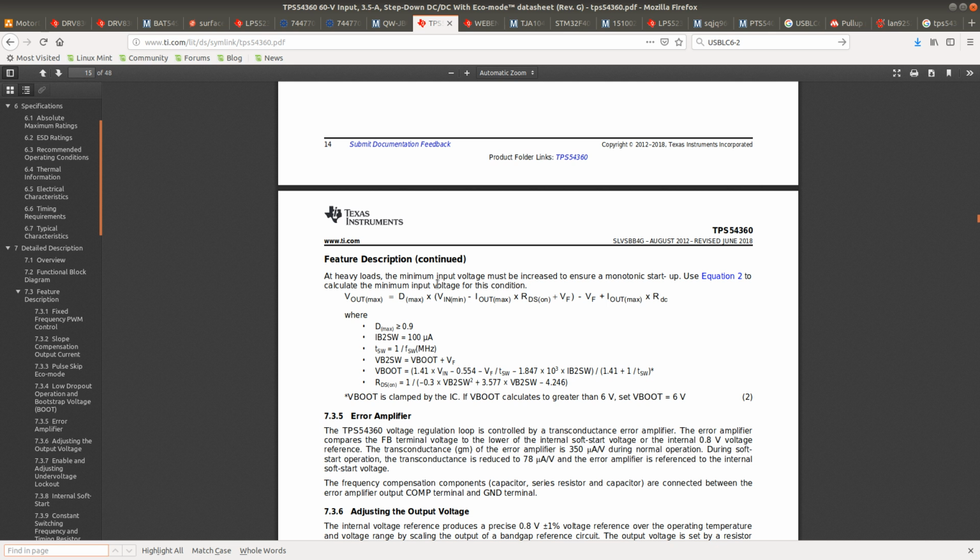And the reason this happens is that the switching regulator works kind of like a PID controller, but for the voltage. So when the load is increased very suddenly, then the voltage momentarily can overshoot the target voltage before it then stabilizes again. So it's important to calculate what our maximum output voltage is going to be.